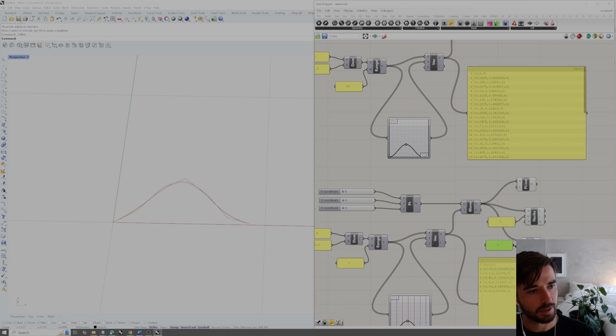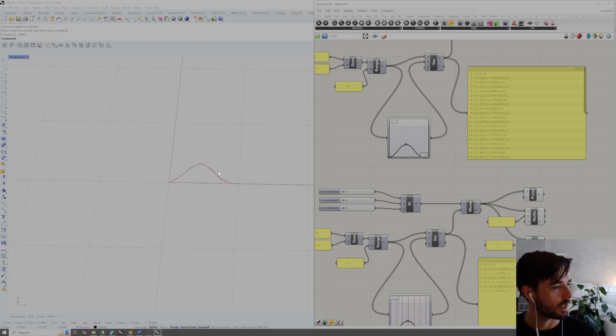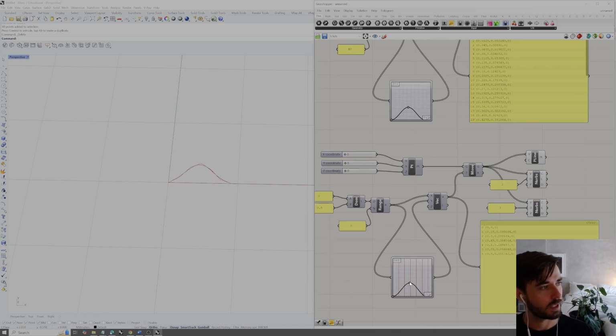And if I copy this down here, we have a NURBS curve that is degree 3. So we can see polyline, first degree, and then third degree. So you can see right there the kind of parametric adjustment. And as we move this, we can see how that changes the differences between each of these curve types.